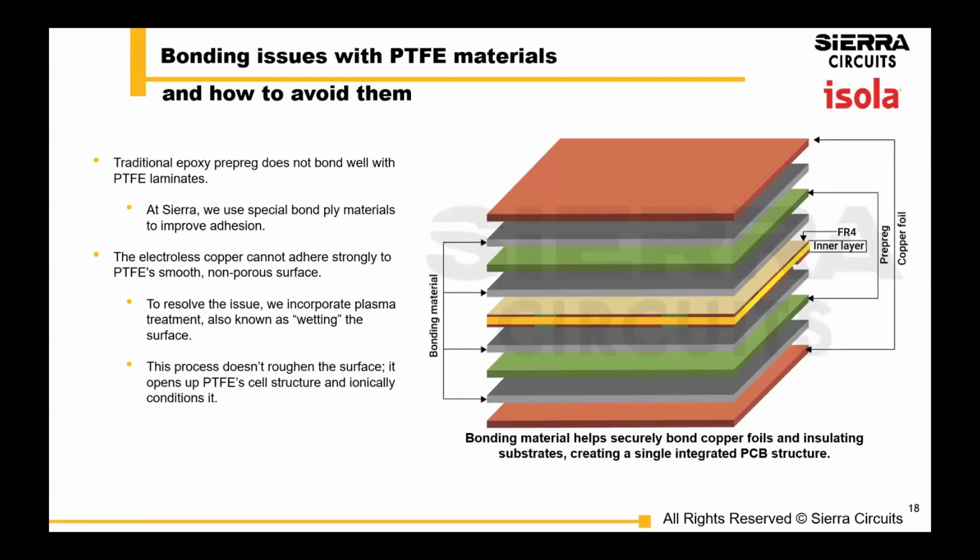Next issue with PTFE materials is how do you bond them? You're going to need special bond plies. So again, really work with your fabricator to understand what your stack up will look like with these specialty materials.